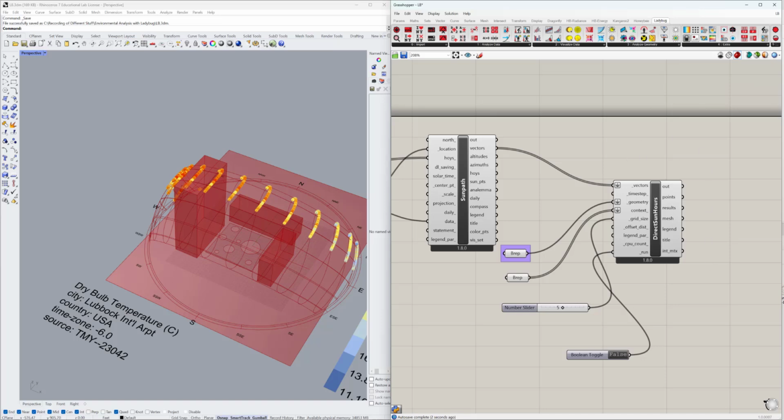Just note that this uses the vectoral calculation, not true radiance calculation. And if you want to get a more detailed and more accurate sunlight hours analysis, you should use Honeybee, not Ladybug. But this also works as a preliminary understanding. So yeah, it's working, so I'll step ahead and show you what it has done after it has done calculation.